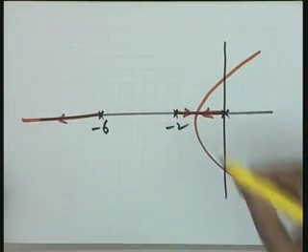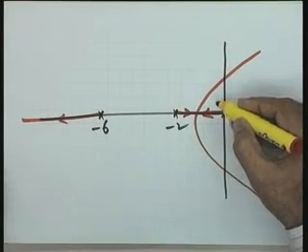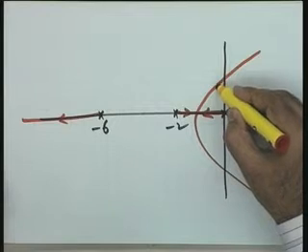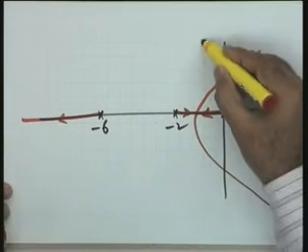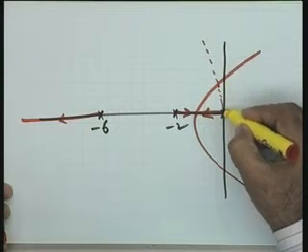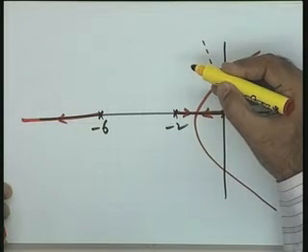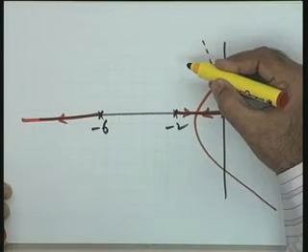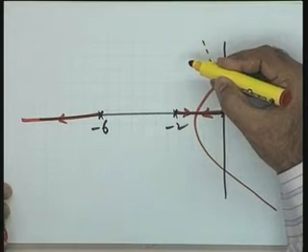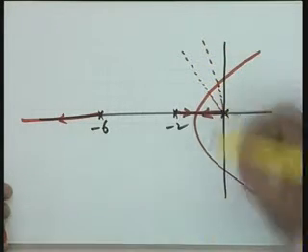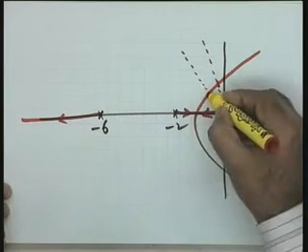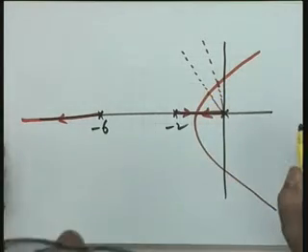Now, you see that if the value of zeta I take 0.15, that is if I take K is equal to 60, the complex roots lie here. If I take the higher value of zeta, that is if I reduce the gain, the value lies here. Okay? If I reduce the gain, but the steady state accuracy drastically goes down.